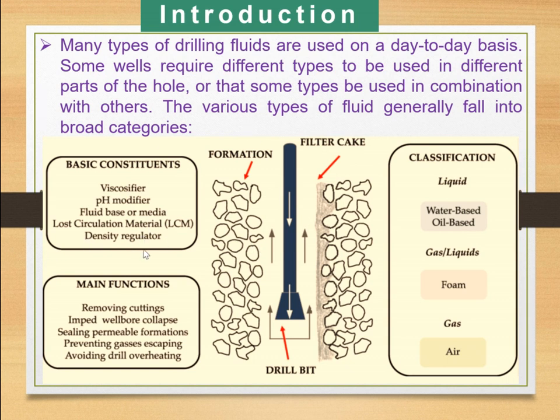And apart from that, density regulator. Drilling mud is often used as a very good density regulator. For example, when you are doing core diamond drilling, when cutting we get a cylindrical core, but of course there will be some cutting materials as well in the borehole. Those materials will create disturbances, so it is very essential to remove them. The drilling fluid acts as a very important medium in taking them out.